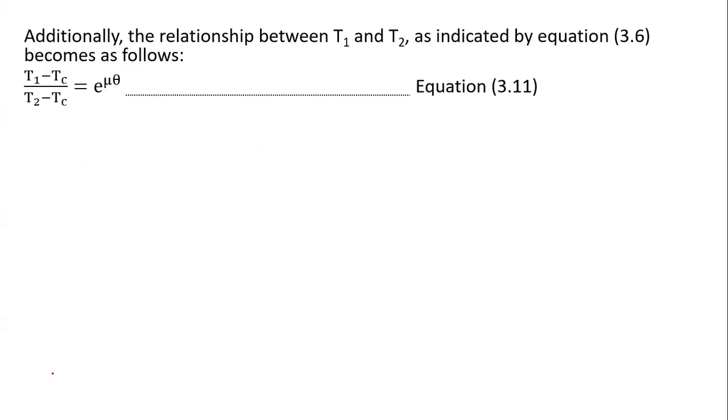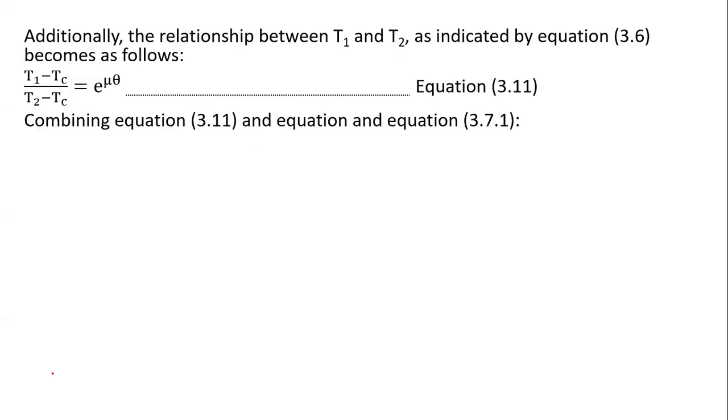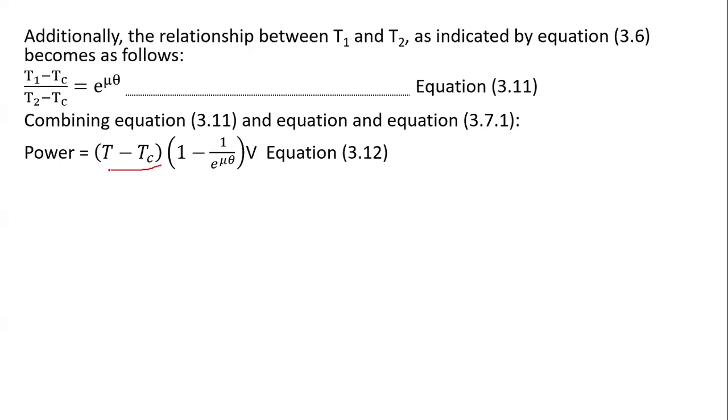Then in case you've been given Tc, it's supposed to be T1 minus Tc, and then you proceed like that, because the centrifugal tension, when it has been provided, you have to take care of it. So going back to the formula for power, in place of T1, you just put the maximum possible tension minus Tc.